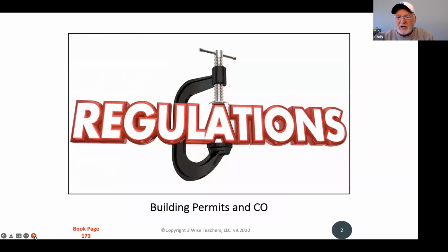A couple of things you'll need to know as we're wading into this is that home construction is based on a North Carolina state law. What if you're in the state of North Carolina? In other words, when you're getting building permits to build a home, you have to meet a North Carolina building code. I don't know if you remember us talking about that in an earlier chapter, but we talked about the state building code for building stick-built houses. And then if it was a mobile home, that's a national HUD code. But anyway, building permits will be on a state and local basis for building a home.